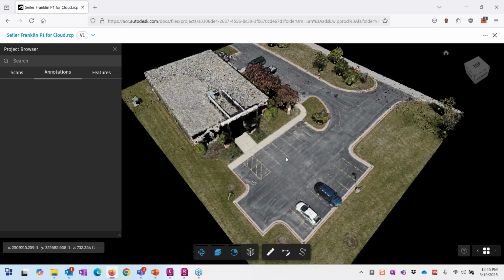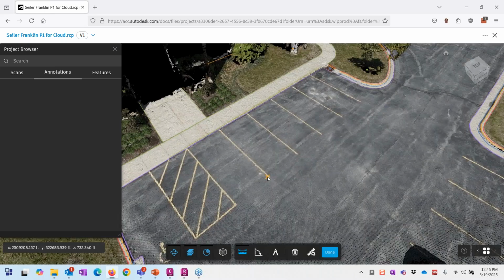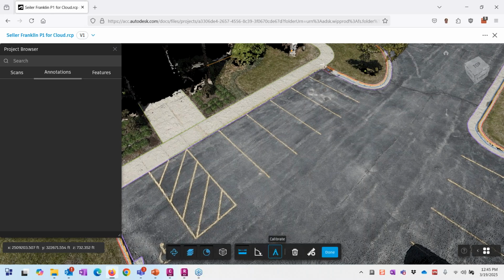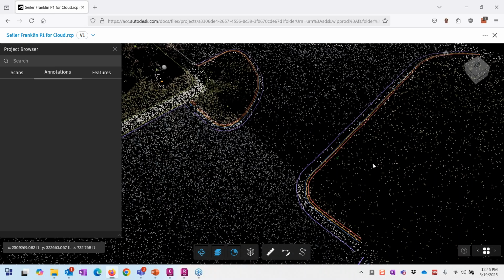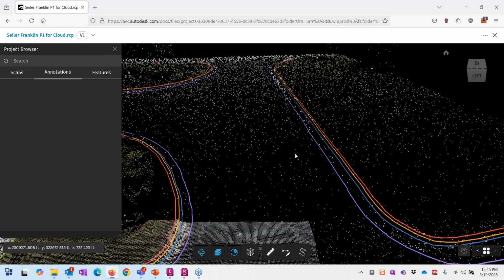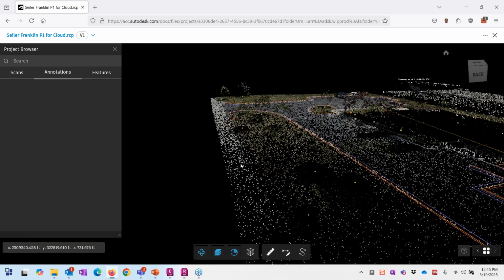Zoom in here a little bit. There we go. So I've got measurement tools in here. Measure here to here, and then I can keep those measurements or I can extract those out as well. They become permanent parts. But Autodesk has also brought in their extraction tools in here. As you can see, I already have some line work that I've extracted from the curb and gutter in here. Their extraction features, let's see if I can run on this curb line over here, one that is fresh.